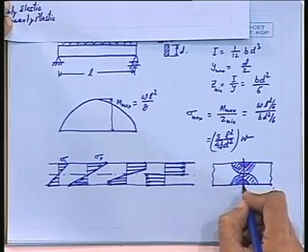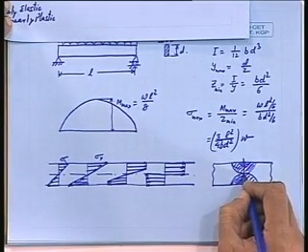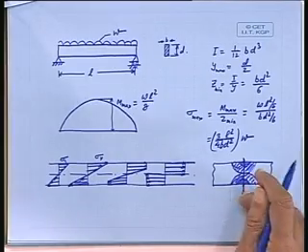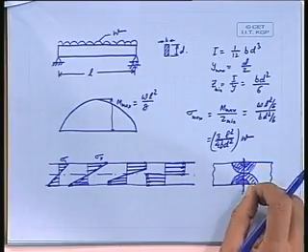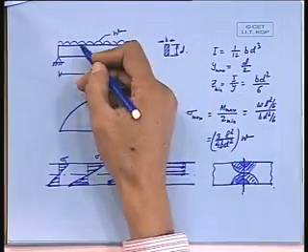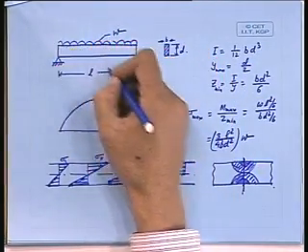That means at this section, not even a single layer or single fiber is in the elastic region. So once this becomes totally plastic, then it cannot take further load, and under the transverse load given here like this, it will simply try to collapse in this fashion. Okay.